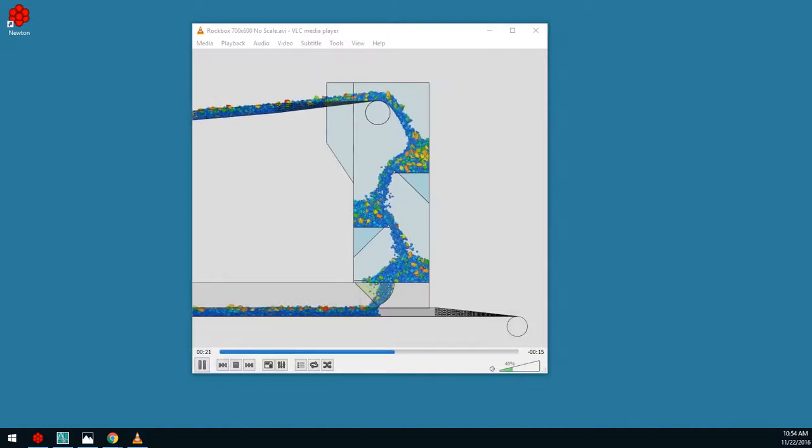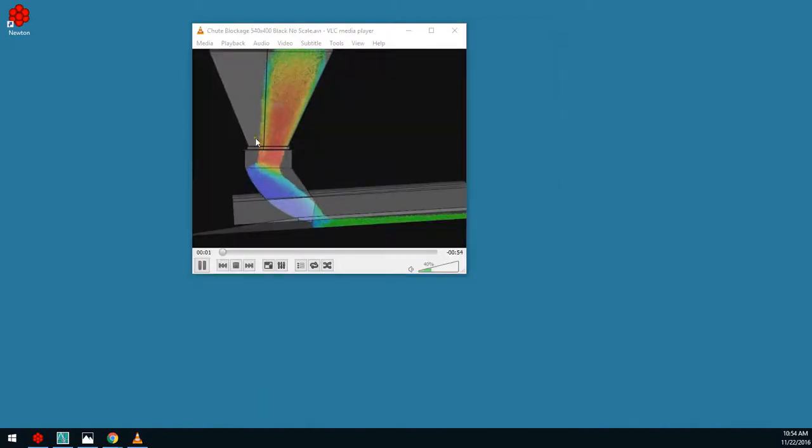This next video is actually a cold transfer with a curved chute on it. Clearly this is the medium to high friction case, and even under that, the medium friction case here, it's plugging up. So obviously that would be an area that we look at and say, okay, what do we need to do to change that design to keep that from building up?